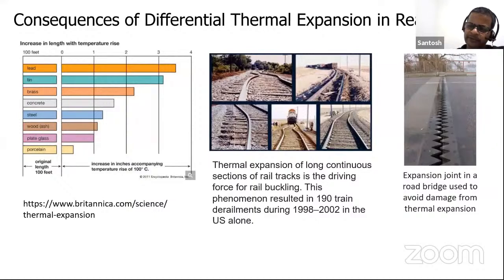Chromium, okay. When you say electronic packaging, basically it depends. I think chromium is used as a metal for metallization. Chromium is a metal, so it's conductive, so it has to find an application where its conductivity plays a role. Epoxy mold compounds and underfills are non-conductive materials. So yes, chromium finds application in packaging, in a place called metallization.